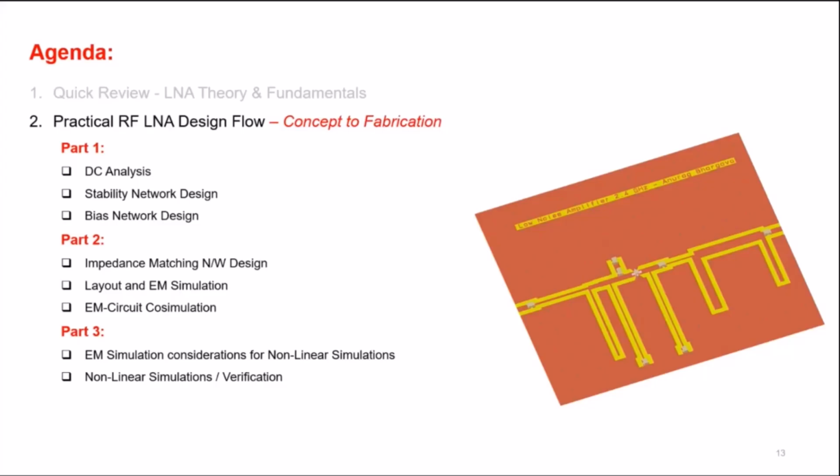Will a PSPICE model of LNA transistor be useful for design? Yes, absolutely, it will be very useful. You can import a PSPICE model into ADS, and it is essentially a nonlinear model, and you can import that into ADS and start designing your circuit with that.